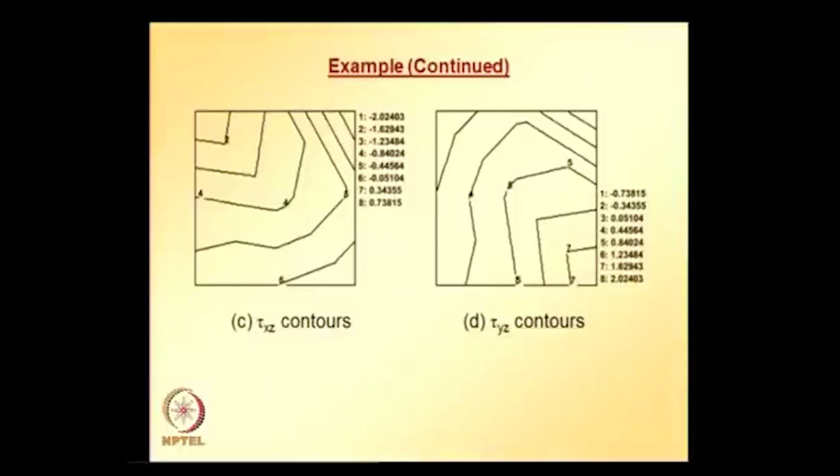Similar to that we did for 4 element solution, we can calculate torque for each of the elements, and then we can find the total torque for the entire square bar, and the total torque when 8 elements are adopted turns out to be 26.67 Newton meter, and the calculation is also repeated by taking 32 elements,